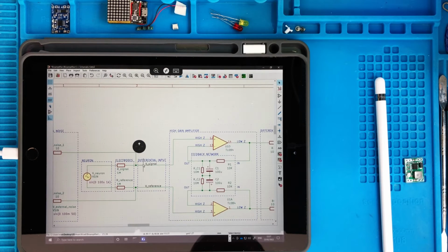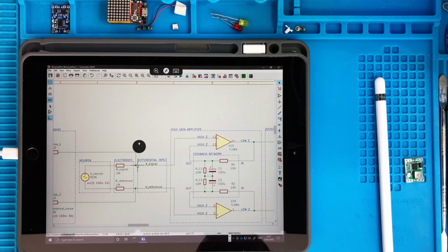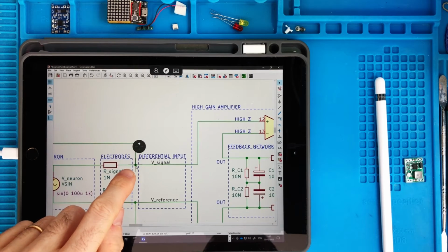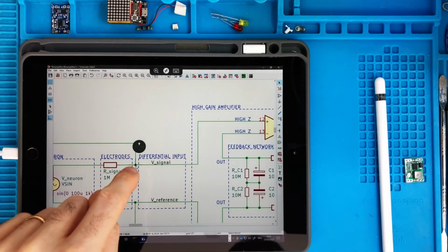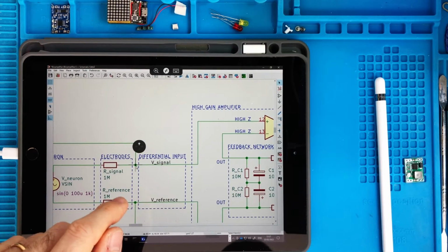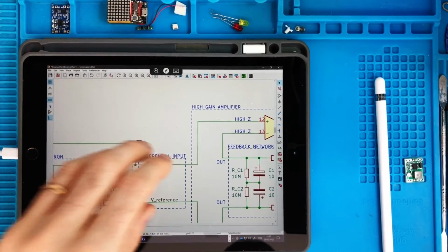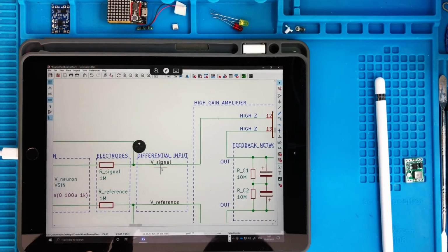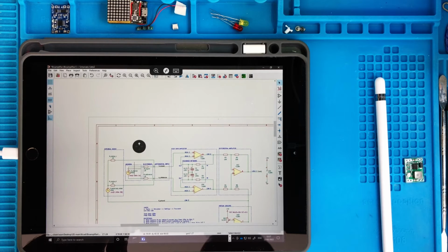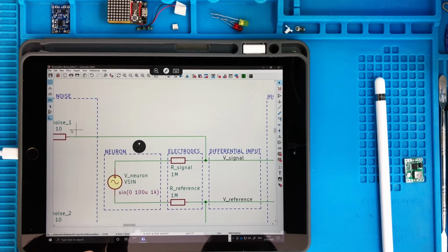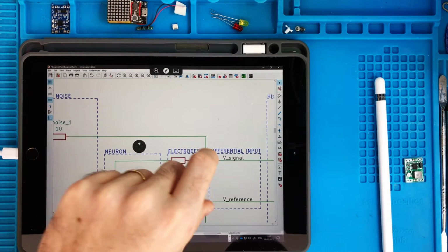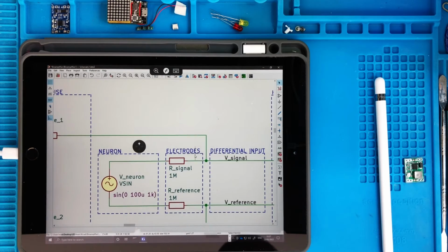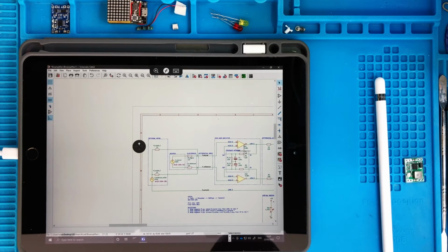I just underline the fact that this connection in this schematic diagram is just topological. It means that it's just a netlist. This node here connected to this node, in fact, they have a meaning for us. So noise can be picked up by this line, and this is exactly represented by these other two things connected here. So the noise in our system will enter from here, from the schematic point of view.